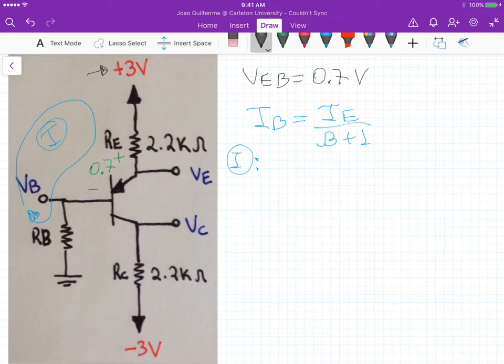We can represent this plus 3 here as a plus-minus with ground that connects to this terminal, and because we adopt the direction of the current going clockwise, we first enter the negative terminal of this voltage source, which is indeed 3 volts. So the first term in our loop analysis is minus 3 volts from the voltage source.